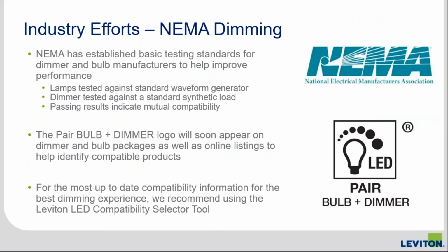So, more on testing, NEMA has come up with a standard for testing, and all the manufacturers, whether it's a bulb manufacturer or dimmer manufacturer, that participate in NEMA test their lamps in accordance with a variety of standards. They test the lamps with a standard waveform. We test our dimmers with a standard synthetic load. And the theory is if they work with these standard loads and generators, they will work with each other.